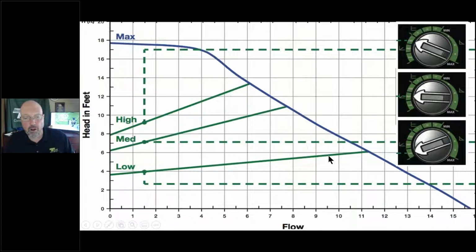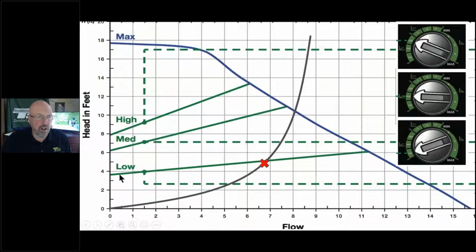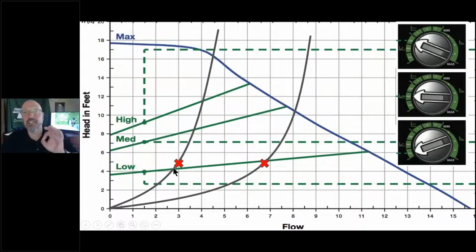So if you all of a sudden say, oh yeah, 7 gallons a minute, 5 foot head, well, I'm going to set it on low and I'm going to slide up and down on this curve here, remembering that this is not for zone valves. This mode is used for your proportional valves, your TRVs, because our smaller zone actually had the highest head, so we would actually be starving it. Now it's so close based upon this picture here, but you see what I'm talking about. We need to make sure that we size this for the proper application. This is not designed for zone valves. Would it change speeds? Sure, it would. But we have the option of doing the constant pressure mode for your zone valve applications.